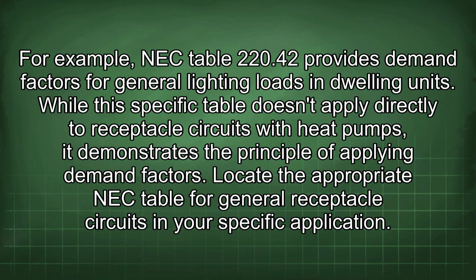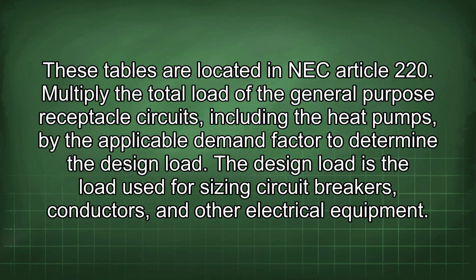For example, NEC Table 220.42 provides demand factors for general lighting loads in dwelling units. While this specific table doesn't apply directly to receptacle circuits with heat pumps, it demonstrates the principle of applying demand factors. Locate the appropriate NEC table for general receptacle circuits in your specific application. These tables are located in NEC Article 220. Multiply the total load of the general-purpose receptacle circuits, including the heat pumps, by the applicable demand factor to determine the design load. The design load is the load used for sizing circuit breakers, conductors, and other electrical equipment.